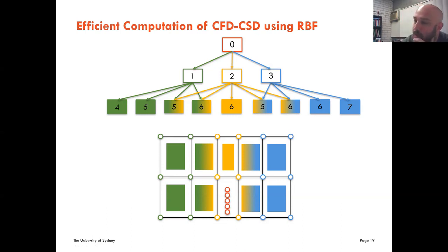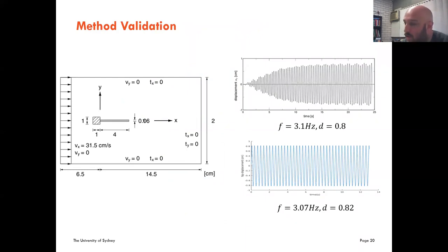One of the students coded all this in, and we applied it to the square Turek model. So we've got a rigid square cylinder with an incoming flow field and a flexible membrane behind. Obviously, the square cylinder will generate a nice vortex shedding structure that will incite the membrane to oscillate. And we get very good results in terms of frequency and displacement, showing that our approach works.